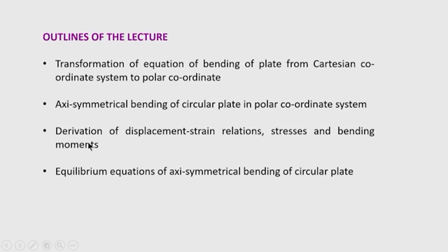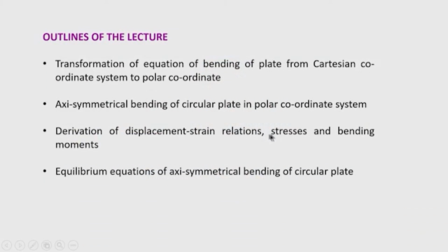We are familiar with the rectangular coordinate system, the bending moment expression for plate, shear force expression for plate, and stresses also we could find. But now, let us see how this relationship will change when we carry out the transformation of the coordinate system. Then we will derive specifically for axisymmetrical bending of circular plate the equations of equilibrium for an infinitesimal element, and from that we get the differential equation for the bending of circular plate with axisymmetrical condition.